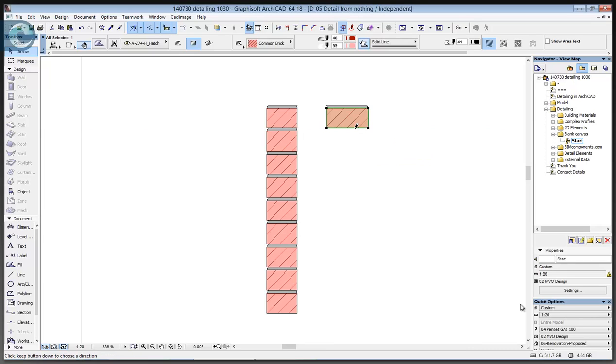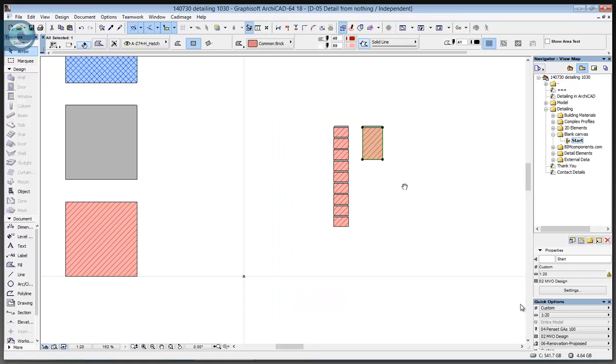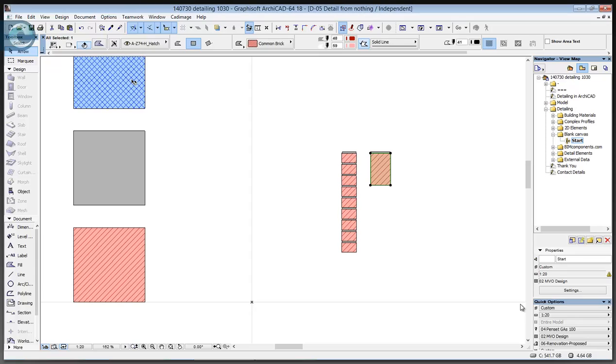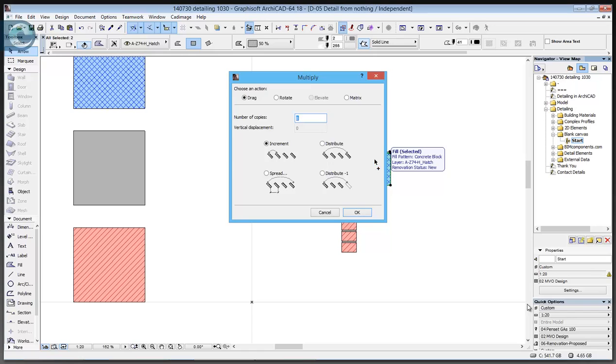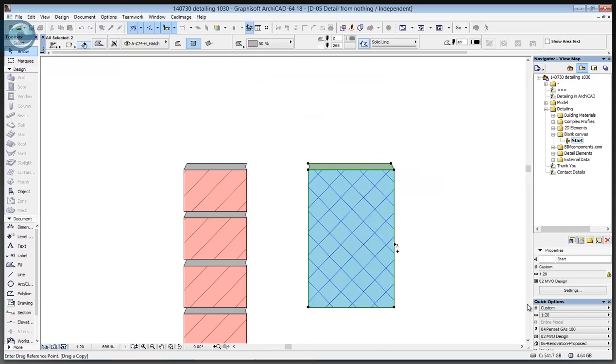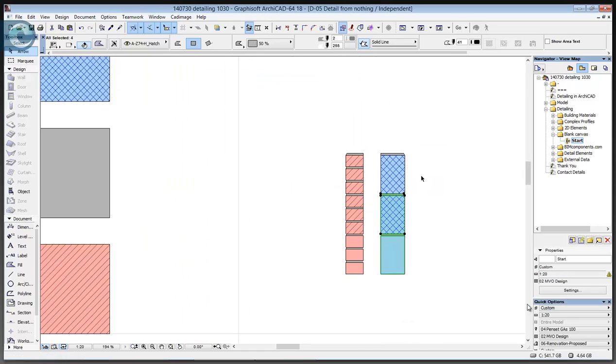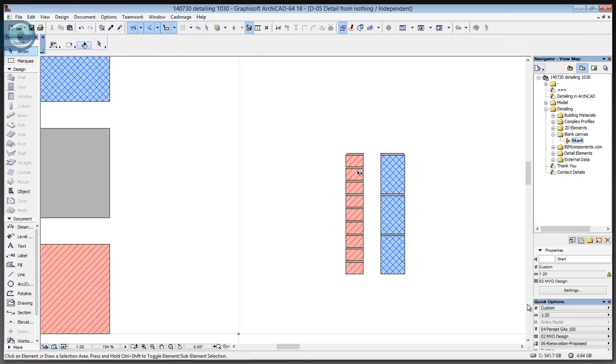And then I'll just take the base and we will offset the bottom edge down to here somewhere. That gives me my odd size brick, but again I can just Alt-click, Alt-Command or Alt-Control, and that drops in, and now it's a concrete block. And we can multiply another 2 copies of this one from the top to the bottom. So I now have my inside face.